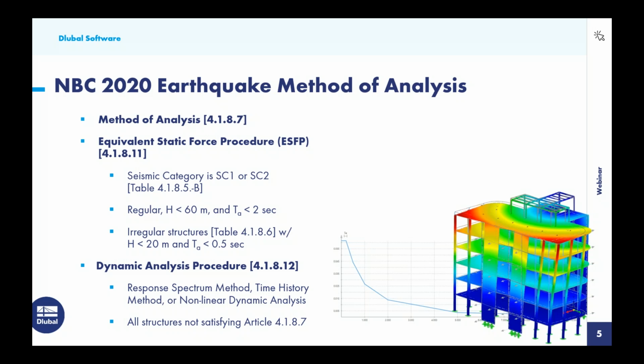Then we have the dynamic analysis procedure in 4.1.8.12, and this includes the response spectrum method, the time history method, or the nonlinear dynamic analysis. And this should really be applied to all structures that do not satisfy the simplified requirements set forth in Article 4.1.8.7. For today, we'll move forward with the response spectrum method for our structure.